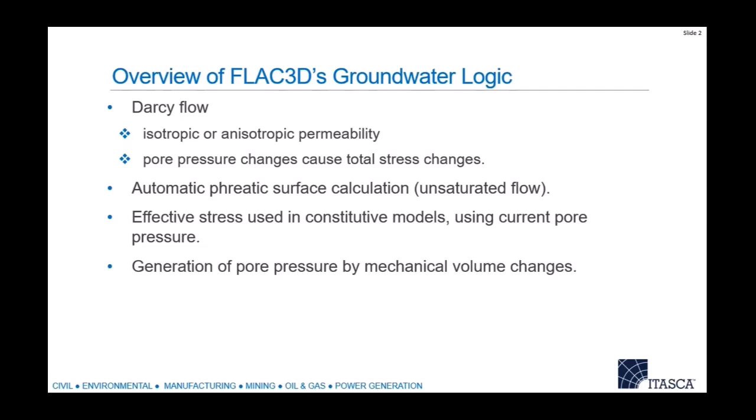The point is the FLAC2D zones are total stress. If you want to look at effective stress and subtract the pore pressure out of it, there's a separate plot for that. You can find it on the list. But the constitutive model always sees effective stress. It's the only thing the constitutive model ever sees. We take that pressure out, pass it to the constitutive model, and add it back in when we're done.